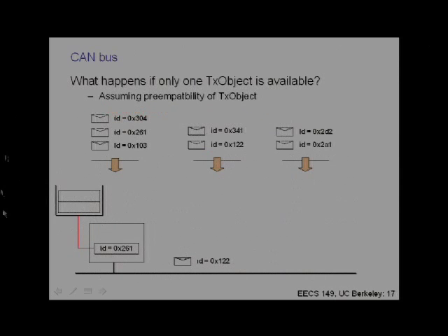Okay, so here you have the same scenario we had earlier, 3 ECUs with a bunch of messages, and each of these are ordered in priority. But let's say that 261 arrived first, so it's sitting in the buffer. And then 103 arrives in the same ECU. Now clearly 103 has higher priority than 261, right? More leading zeros. So it's going to preempt that message. Okay?